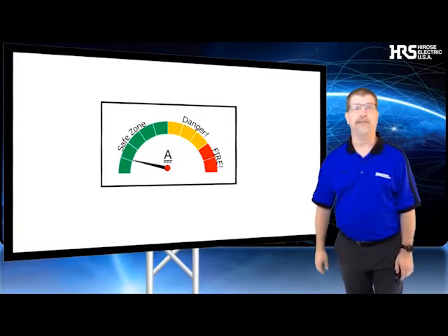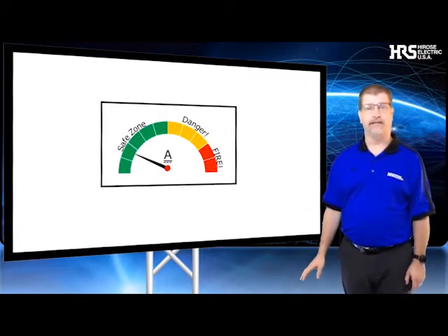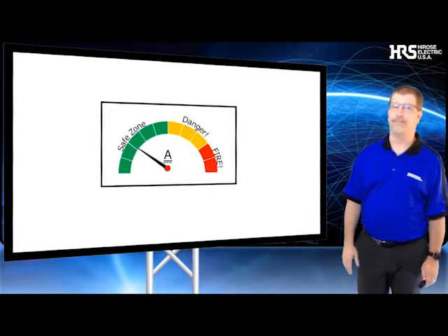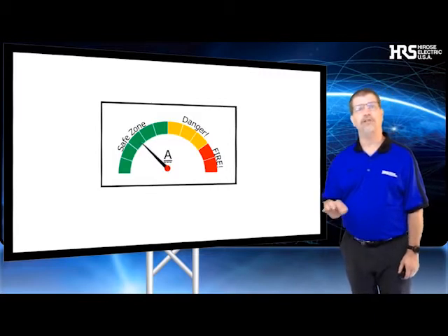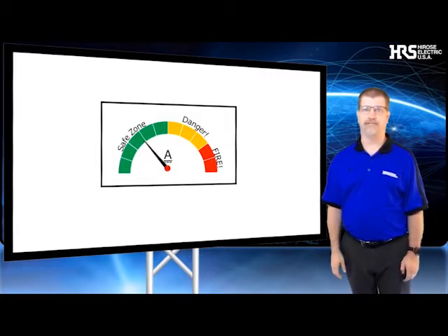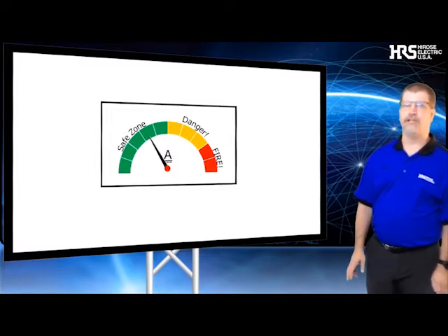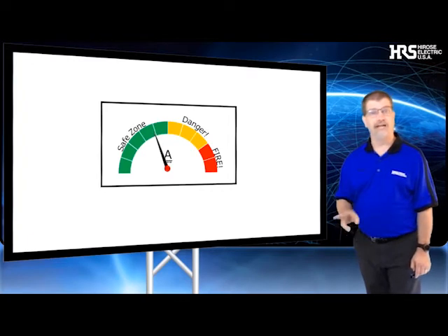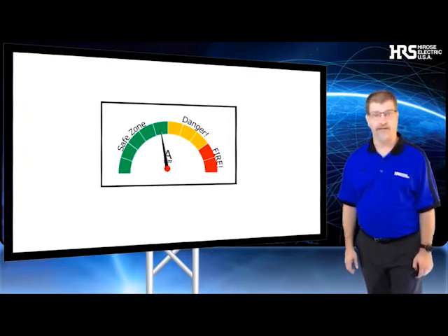However, let's say that you plan to divide a single 10 amp circuit across more than one contact. The initial thought is you only need 2 5 amp contacts, but the reality is a bit different. When current is divided, we will not know exactly what the contact resistance is at each connection point. This is not the same as drawing 2 completely independent 5 amp sources. 2 side-by-side contacts could have slightly different contact resistance values.